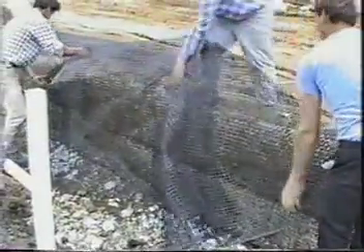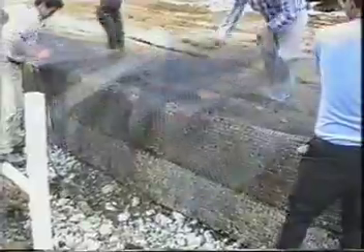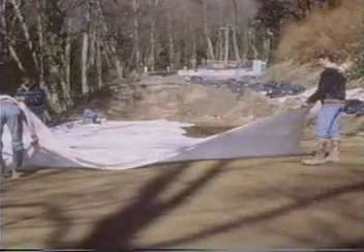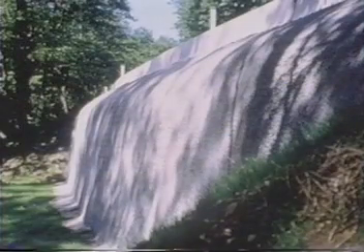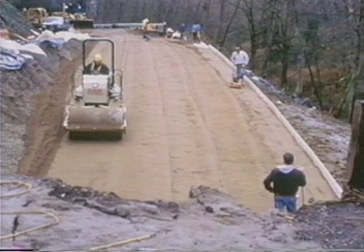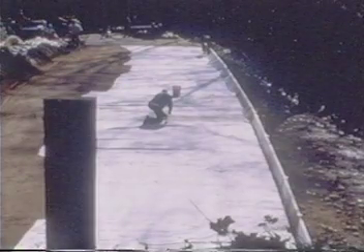The simplest form of soft facing is wrapped facing, in which a geotextile or geogrid is wrapped around the face of the fill to form an envelope. Here we see a layer of geotextile spread out so that its free end extends over the face of the wall. A layer of fill is placed and compacted over the geotextile reinforcement up to the line of the face. The free length is then folded back to encapsulate the face of the layer of fill.